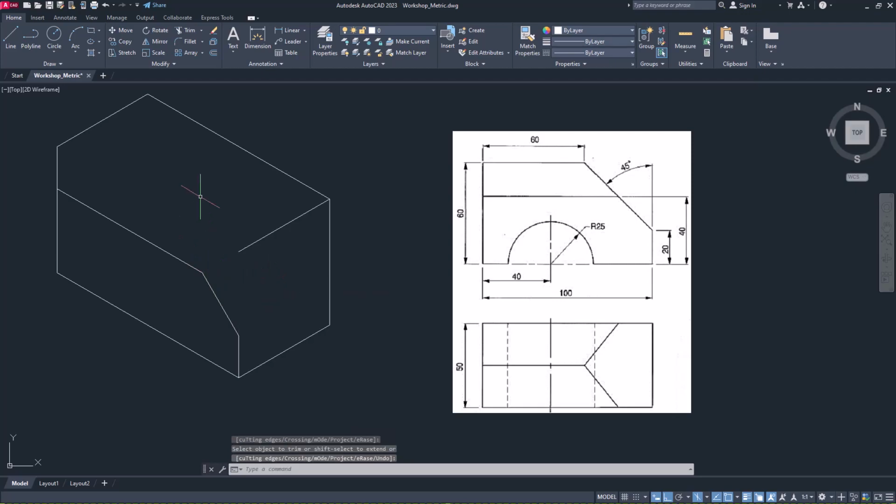Okay, now similarly draw this vertical line downward by 60 and copy this part, this part, this part and this part from here to here. Okay, now let's remove this unnecessary part. Now let's try to create the center part. So here from the middle this will be 60 millimeter. Okay, now let's remove this line and join this line from here to here and from here to here.